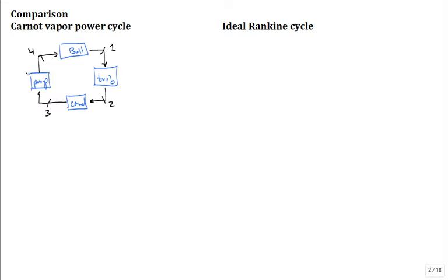And then we try to say, we want all of the heat that comes in to this boiler to come in at the high temperature TH. The only practical way to have that happen is for when all of the heat is coming in to the working fluid and the working fluid doesn't increase temperature, the only way for that to happen is it boils. At constant pressure, it's going to change phase.